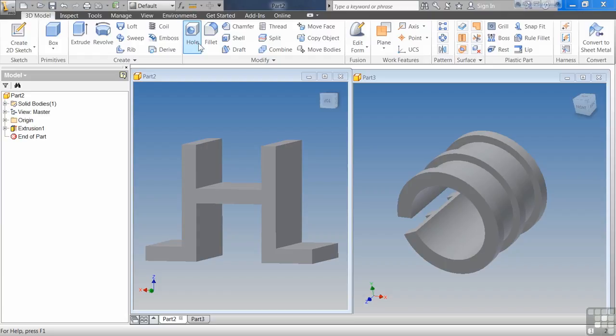Because most 3D models include some combination of extruded and revolved features, a basic understanding of how to create them is essential for successful model creation. You can create most 3D models by combining multiple extruded and revolved features. You start by creating a 2D sketch that represents the basic shape, and then use different feature creation tools to turn that 2D sketch into a 3D feature.